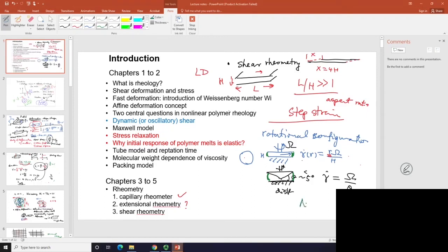In the nonlinear response, we have hardly talked about yet. When you shear very fast and shear a great deal, you meet an enormous problem that nobody on Earth knows how to solve. In other words, our shear device is far from a perfect apparatus because of the free surface that's inherently there. If you guys have an idea about how to get rid of it, let me know, because you should be able to make a pattern on it and move the science forward.